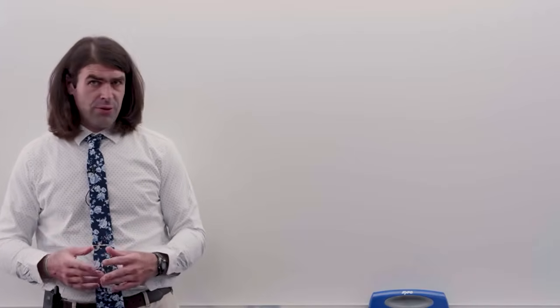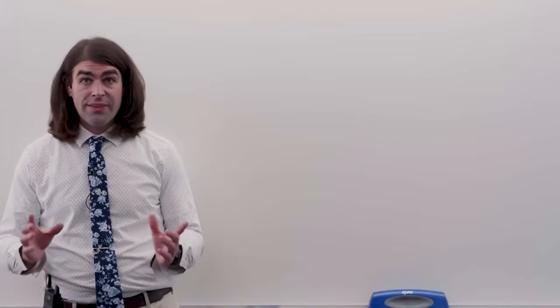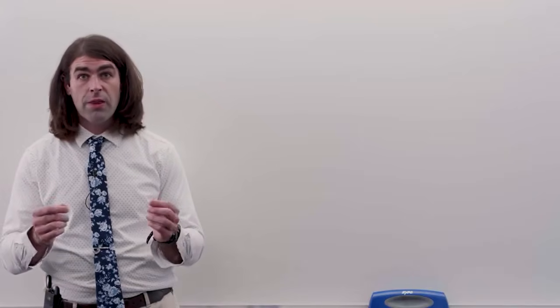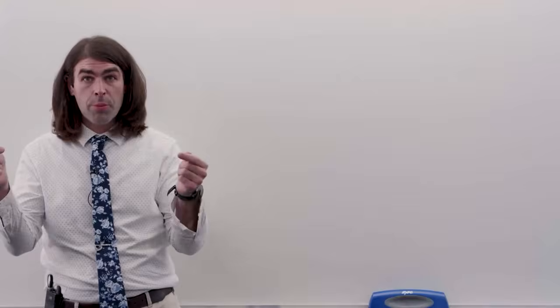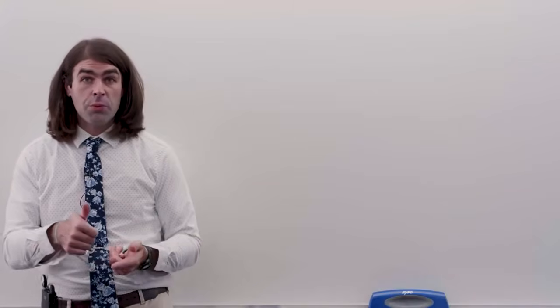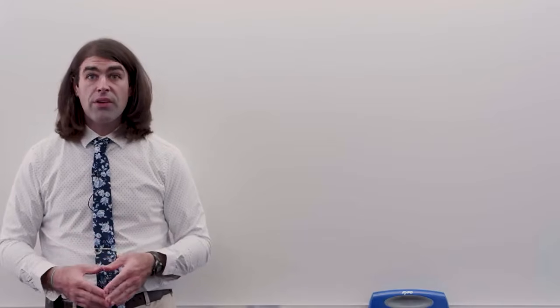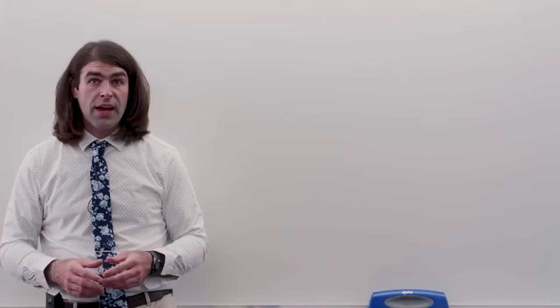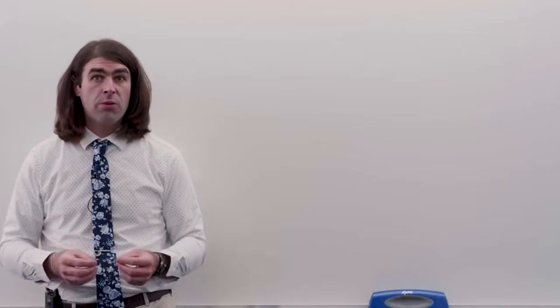The other thing, and of course in the ASME standard it's a long definition, but basically it's opposing points you're looking for. So a cylinder has opposing points you can measure, whether it's an external or an internal cylinder. So, a caliper can measure inside out, or a caliper can measure outside in. So cylinders, spheres, widths, slots, grooves are all features of size. What isn't a feature of size is a chamfer or a fillet, because there's no opposing point to measure. Those would not be able to be controlled in the ASME standard with position.